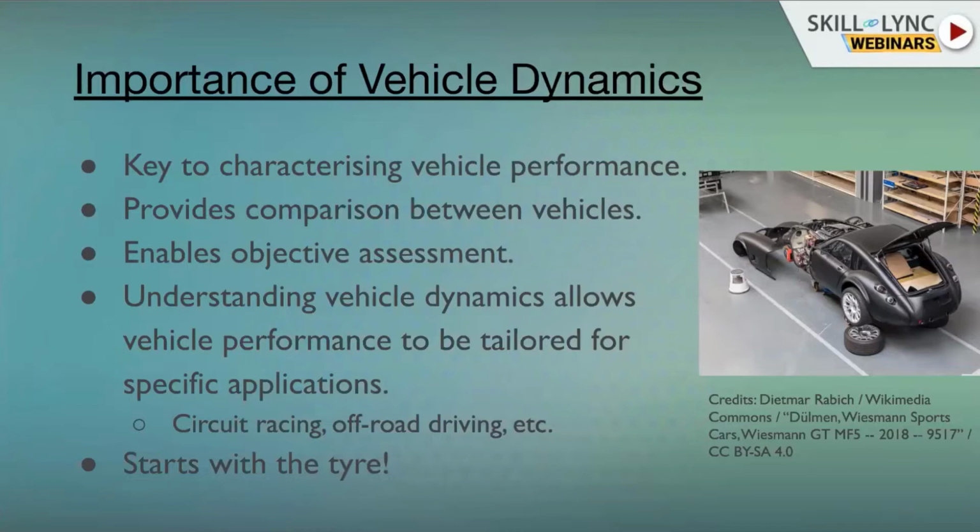You have subjective approaches, which is like the driver commenting it's too much body roll, for example, not compliant enough over bumps, too much vibration coming into the steering wheel. These are all subjective. But the advantage of the objective approach is that you can put numbers on things.